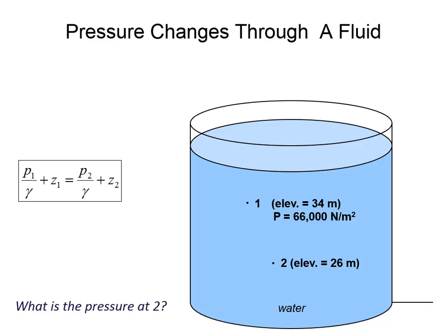And so even if you left it in terms of pascals instead of kilopascals, it would probably be more accurate to say that the pressure is going to be 144,000 newtons per meter squared rather than 144,480, because the data we started with doesn't justify claiming 1, 2, 3, 4, 5 digits of precision. All right, other questions? That's a good question.